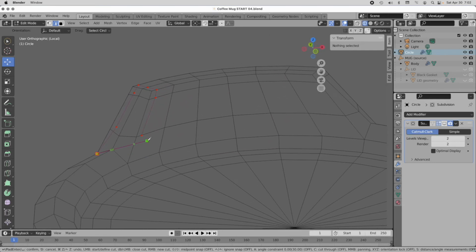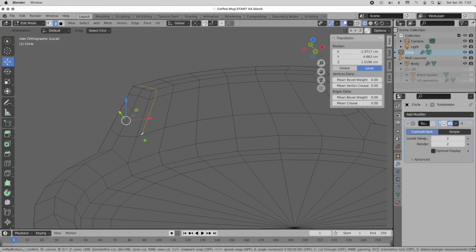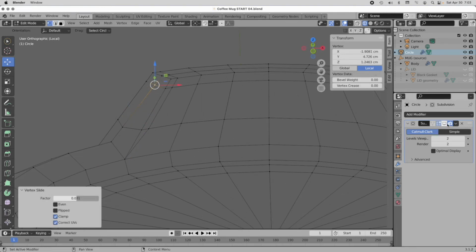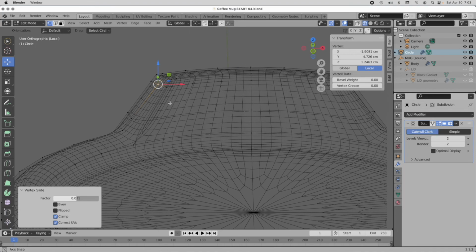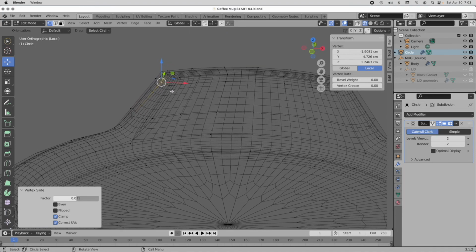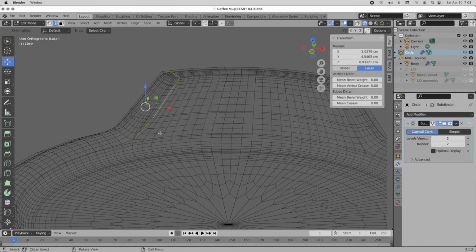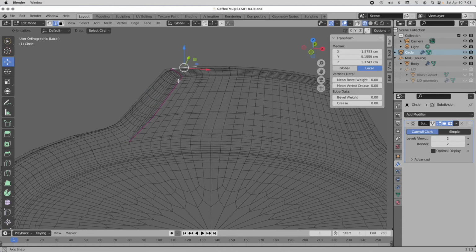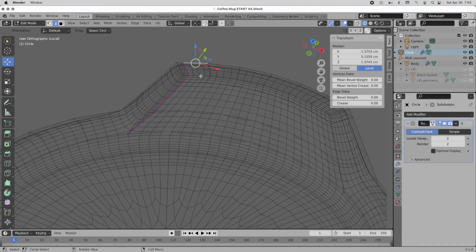Now I'm going to hit Enter, K key again, and we'll just click here and go to there. Enter key. And so when we turn on subdivision again, it gives us just a little bit of a harder edge to work with. In fact, this is where we could also come in. Let me double click that loop, and we could also use that crease function, Shift E, if we wanted those subdivided polygons to be a little bit more close, but it's such a short distance that it's not likely something that you would see. I just wanted you to become aware of that.